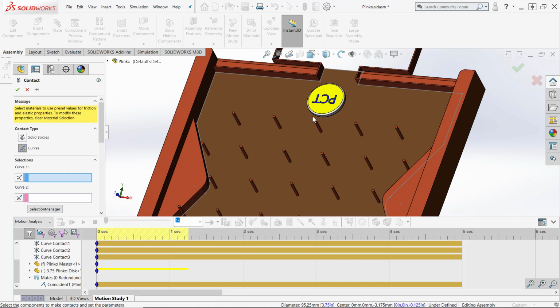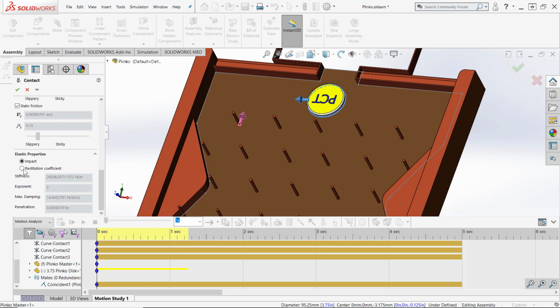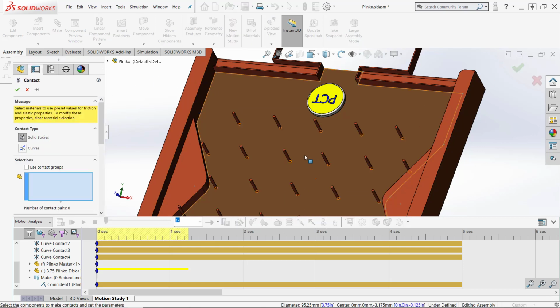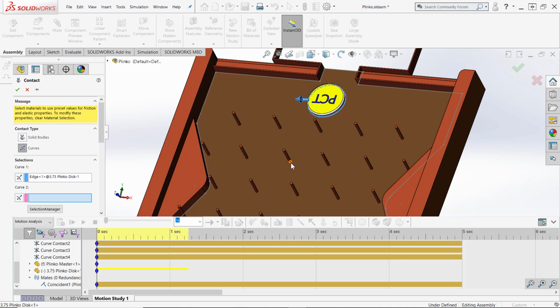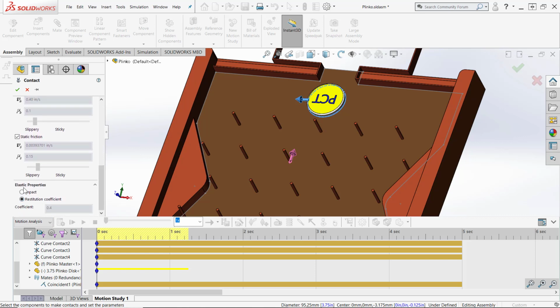2D contacts. And so I'm not sure if you have a simplified technique for doing those that you might want to demonstrate. And let's just do a couple more, and then I'm going to get tired of doing this. But anyways, it is something that would have to be done. Now I tried doing the solid body contact, and that just locked up SolidWorks when I gave that a try. I'm not sure if there's some tips on that you might have.